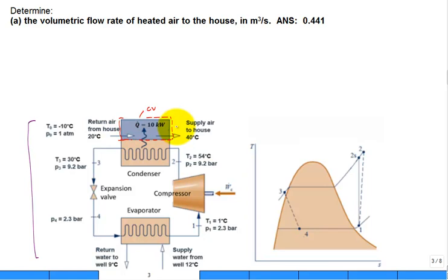And so that just is going to be heating. So one mass flow rate in, one mass flow rate out, just of the supply air. And so what we find is that the Q dot from the condenser, 10 kilowatts, is equal to the mass flow rate of the air times the enthalpy change, enthalpy exit minus enthalpy inlet for the air. And the standard assumption, lacking more information, is to just use a specific heat. So mass flow rate of the air, the specific heat at constant pressure, C sub P of air, then you have the temperature exit minus the temperature inlet of the air.